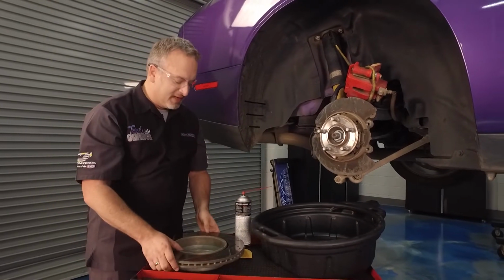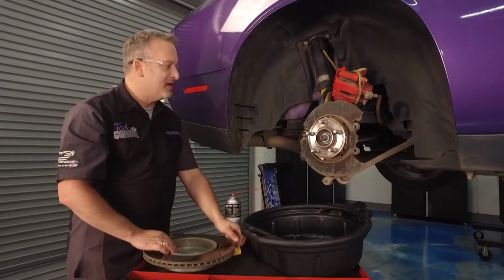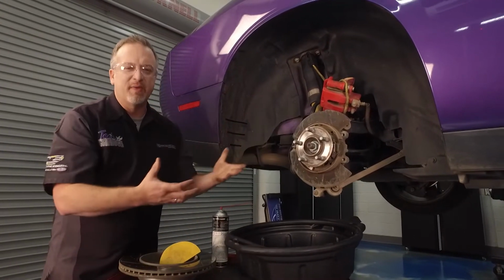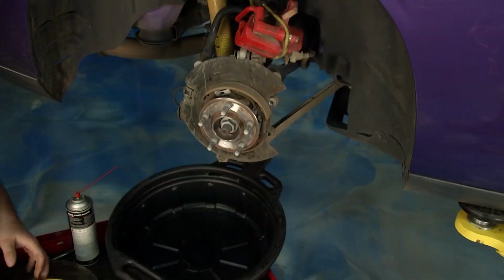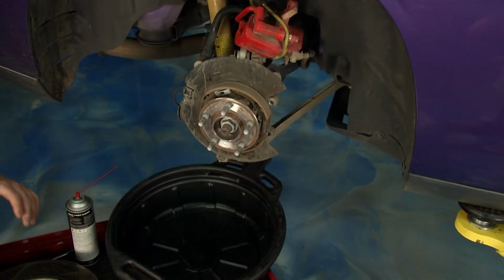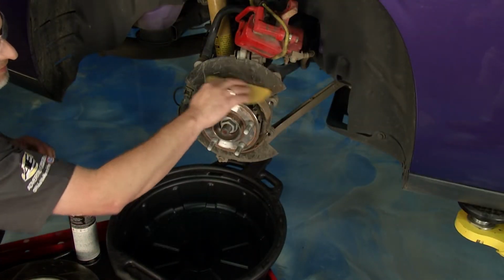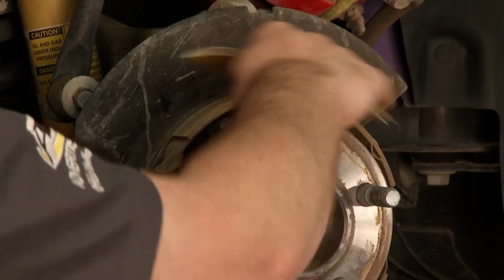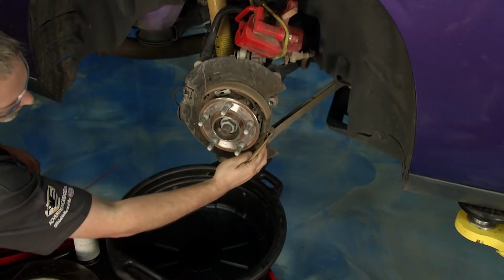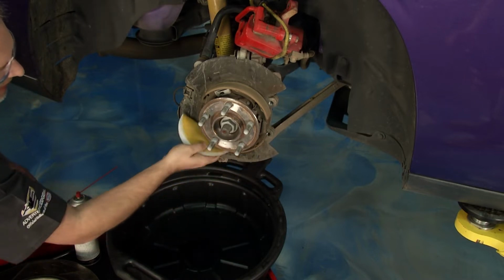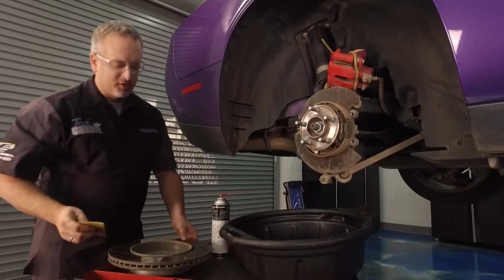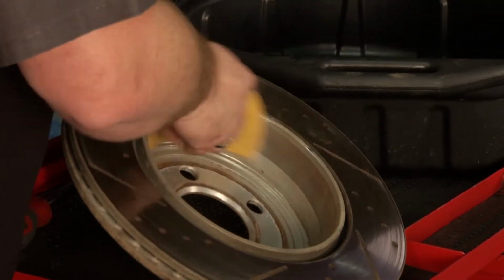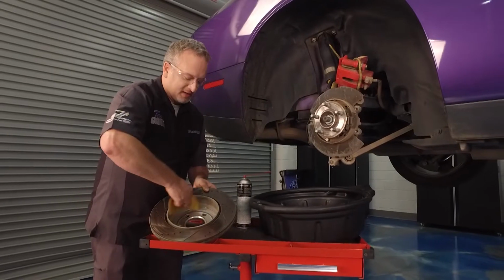Now that we have our disc and drum system pulled off, we want to take a look here at our shoes and see if there's any debris in there. It's going to be some obvious stuff when you do the visual inspection, and this looks pretty good. So we're going to start sanding here. We're going to make sure we have a good coefficient of friction, get some of the dirt off of there and get a nice even surface for our drum to grab onto. And then we'll do the same thing over here on the drum as well. You're going to sand around the entire thing to make sure that we have a nice grippy surface, and then it's going to help us stop.